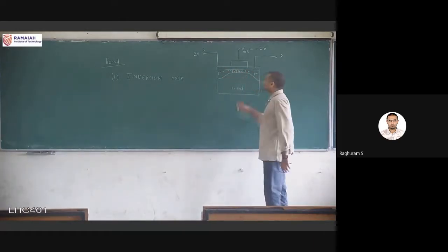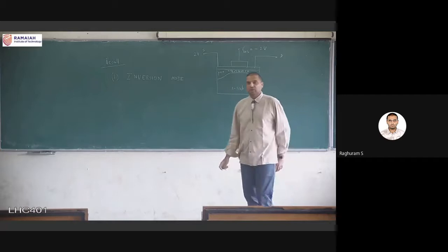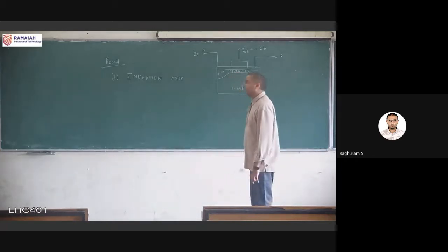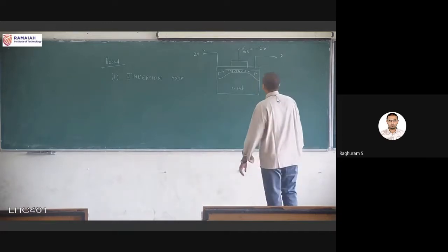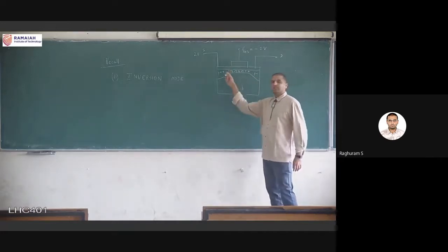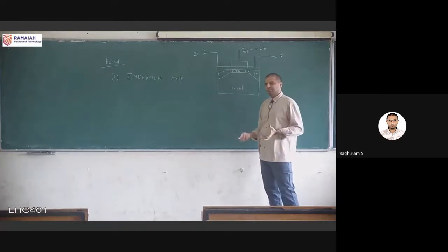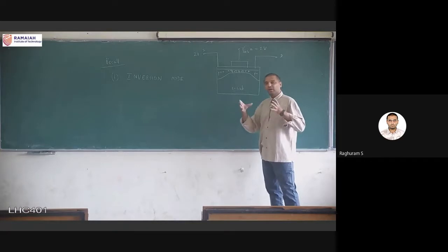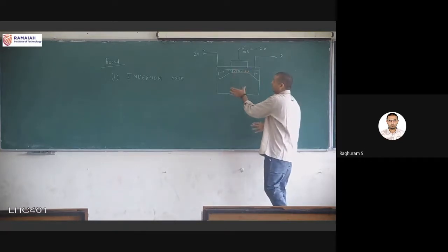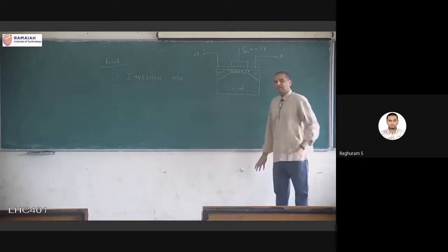This middle part is also called the channel region, directly under the gate terminal. In a p-type transistor, on the left hand side and the right hand side, the source and drain terminals are of type p plus. That is, there is a region that is fabricated that has a lot of holes. And in between, it is traditionally an n-type substrate.